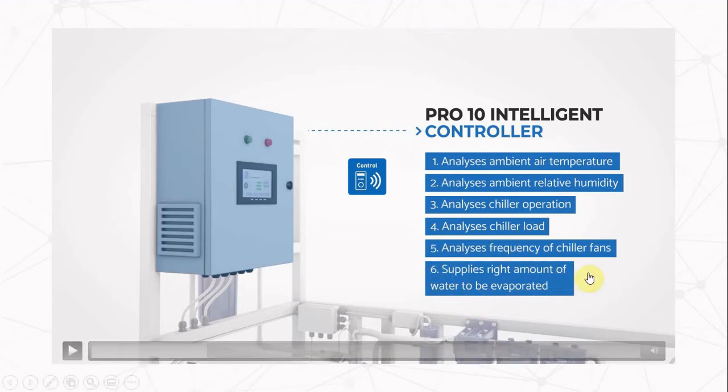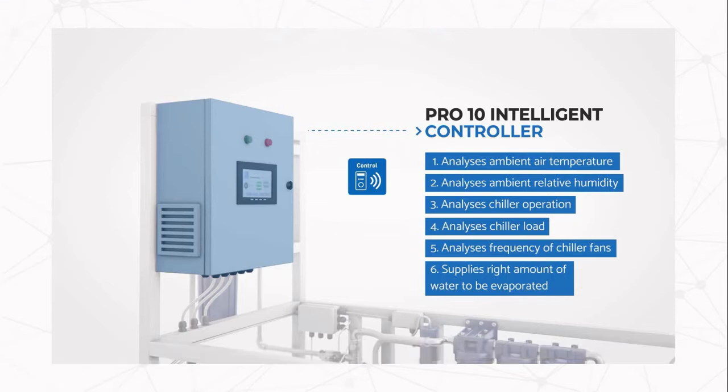If you oversupply, it may lead to extensive water dripping or leakage, which might ultimately harm your chiller roof or chiller's frame. On the other hand, if you do not supply the system with enough water, the system will not be efficient. You might end up with only 5 degrees temperature drop instead of a 15 degrees Celsius temperature decrease because not enough water was used. Once the outside temperature has reached 23 degrees Celsius, the equipment turns on automatically and operates according to the parameters we have discussed previously.